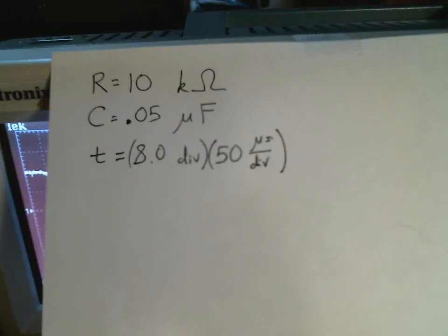So summarizing our results with the known capacitor, that's what we had. And if you work those numbers out, it's not great agreement. It's about 20 or 30% off compared to the value printed on the capacitor and the value that we roughly confirmed on the meter. So most likely that's because there's stray resistance and stray capacitance in the circuit, such as the resistance and capacitance of the input of the scope.